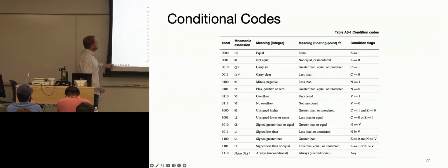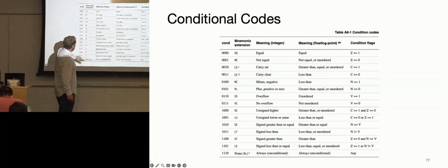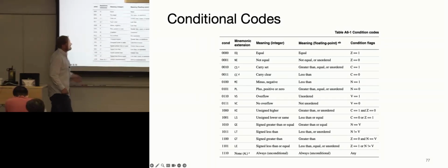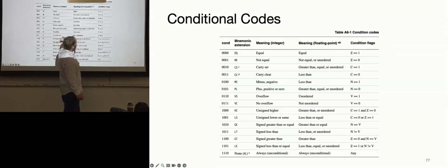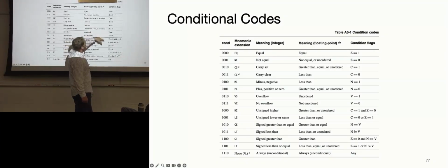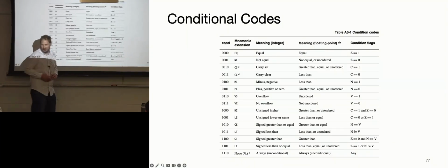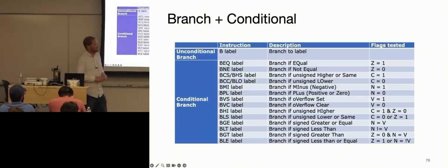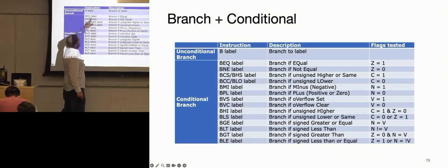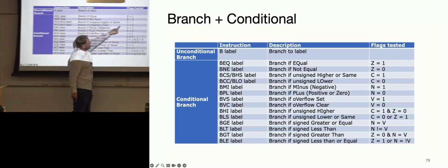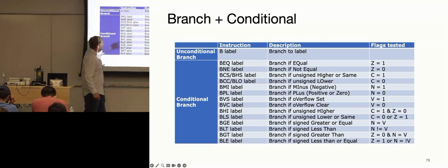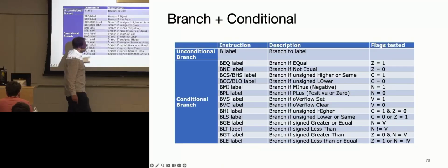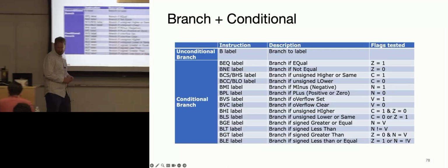But you can modify all those instructions with conditionals. And where do those conditionals get set? Those conditionals get set in your ALU flags. Previous instructions, like an add, can set that flag, and then you can use it in a conditional. So you could have branch equal, denoted as B equals a label. If this condition is set, then you actually execute that branch. And there are all the possible variants you could imagine off of those ALU flags.